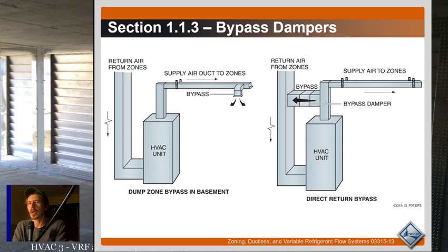Now there are other problems associated with it. Especially the larger the motor gets, the more dangerous this situation is. But in general, on small fractional horsepower motors, whether they be in a pump system or in an air handler, deadheading that motor causes no problems. It can't do any work, so it just freewheels.